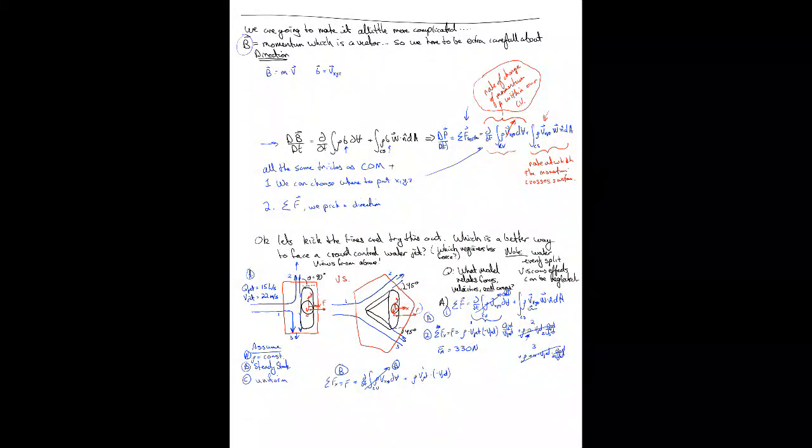And the second velocity is the velocity of the jet relative to our control volume dotted into the control volume normal. It's a lot. But this one is negative, and multiplied times an area. But again, our area is just q jet over v jet. Sorry, not divided by 2, because it's the whole jet.